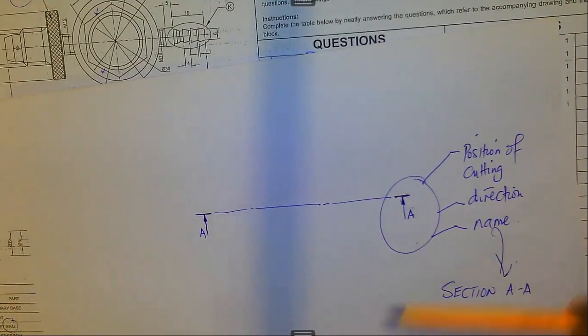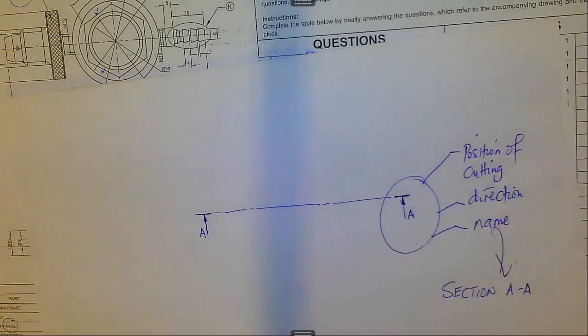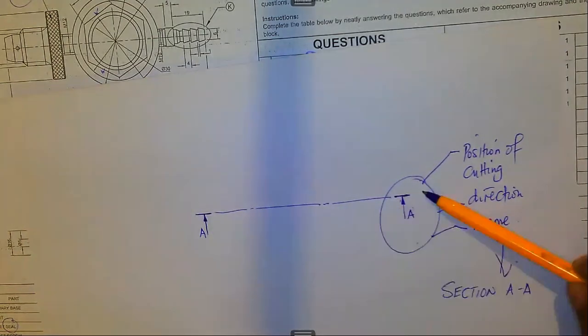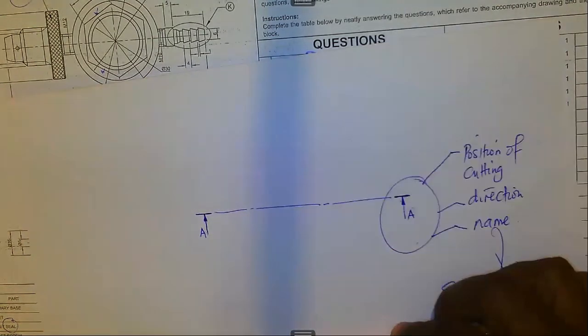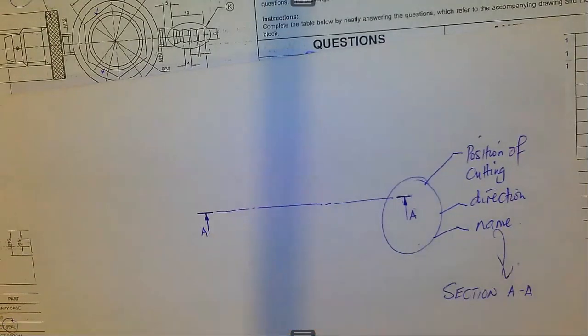Where the tail is coming from, that's where you are throwing away everything. So you have got the part that has been cut, right? And you throw away everything that is on the tail side. Remember, this is basically theoretical. You are not going to physically cut or physically throw away anything. It has to be imagined that if an object has been cut, what would you be able to see? That is the function of a cutting plane.